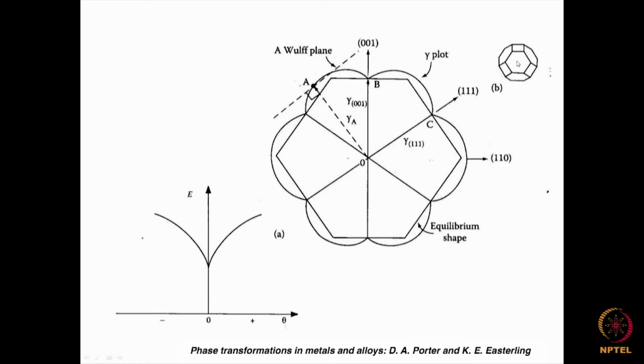This is the 3-dimensional one. That is essentially the surfaces, which has 100 as well as 111 type of surfaces, correct. The normals, if you see, this is corresponding to the 111 plane, this is the 001 plane. And the ratio between the surface areas of the crystal which has formed is equal to the ratio between the surface energies for those two planes. Okay.